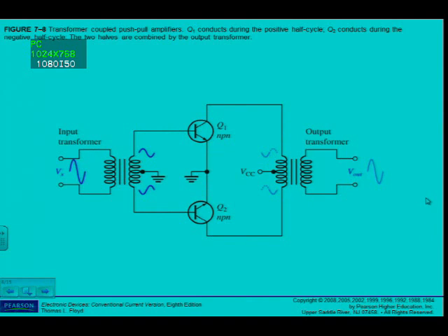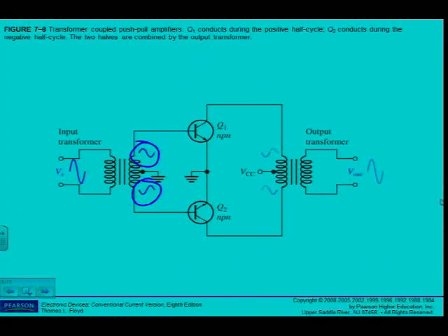you can see the transformers. What type of transformers are used here? You used them in electronics 1 for full wave rectification. Center tap transformers. Can you see that? Characteristic of a center tap transformer on the secondary side: two waves, 180 degrees out of phase. Same principle that's been used on the full wave rectification.